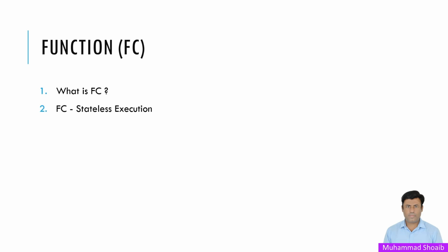So some FC characteristics. FCs are stateless executions. FCs do not store or retain values between cycles. Each time an FC runs, its internal variables are reset. For example, a function that calculates the sum of two numbers does not remember the sum in the next PLC scan cycle.